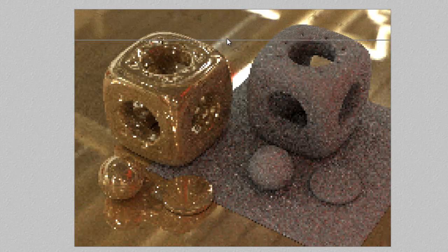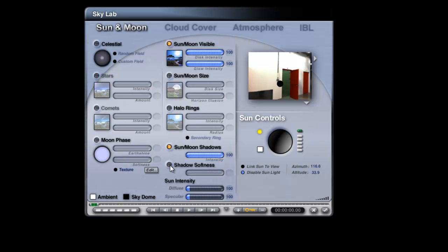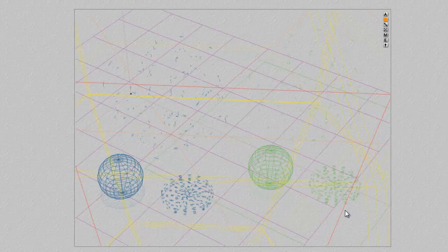So we've stopped the true ambience lighting but allowed the reflections to come in, so we still get our reflection effect. At this point now consider upgrading the light effect from the sun, so I can get the specular, but I don't need the diffuse side because I've provided the diffuse light. So I'll enable the sun but only provide a specular. This will give me specular highlights on the material.